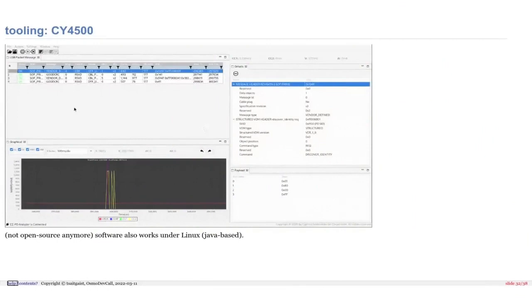So this is what we see in the beginning. Again, we have 4 messages. We have the identity request. I've selected it, and we see the discover identity request. Then the second message is a good CRC, so it's the ACK. The third message is actually the cable replying to this identity request. We'll have a look at the reply afterwards. It is sent by the cable, and then the power meter will send that good CRC telling, okay, I received the response. If it doesn't receive a good CRC, then the cable should send this identity a couple of times before it stops.